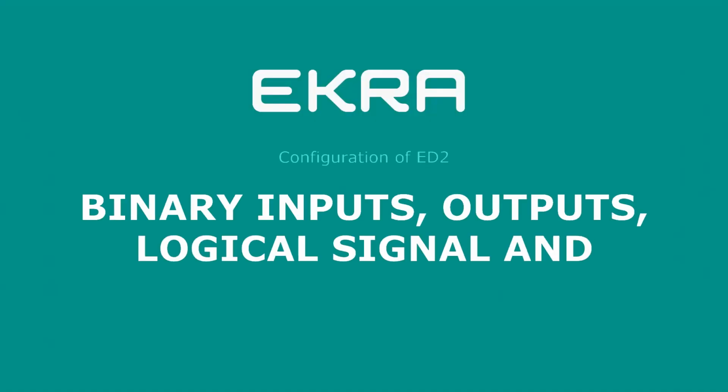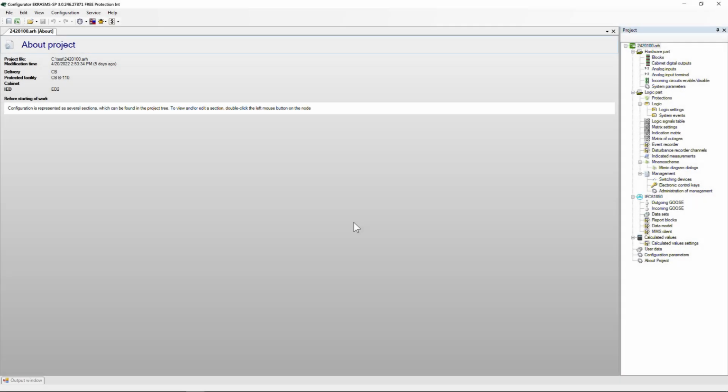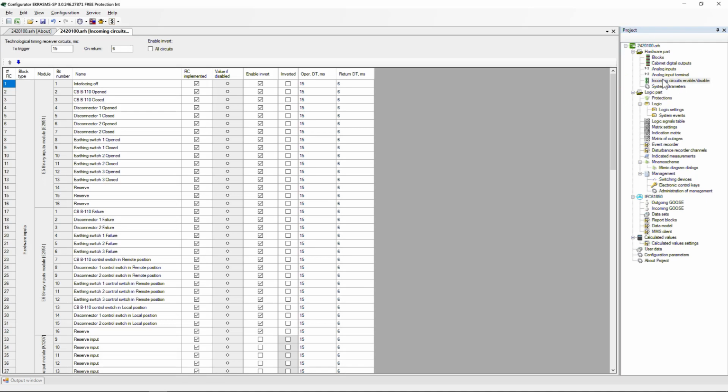In this video tutorial, you'll learn how to change input names, reconfigure binary outputs and LED indication, and specify event recording, disturbance recording, and perform other signal settings. Before starting to work with the configuration, it is recommended that you watch the video tutorial opening and saving of configuration file. To edit binary inputs of the IED, open the Binary Inputs section.